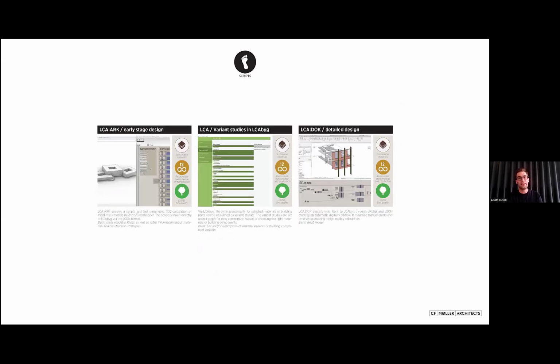And then finally, the LCA. This is something that, well, this part is not something that we do ourselves in the early stage competition, but it's something that we are informing our designs with. So our sustainability team, they take our Rhino model and then they run our own LCA calculation tool to give us insights of, for instance, how much we should push for a different construction type, or if we're dealing with transformation projects, so we are on track of how much CO2 we are spending with each design decision.